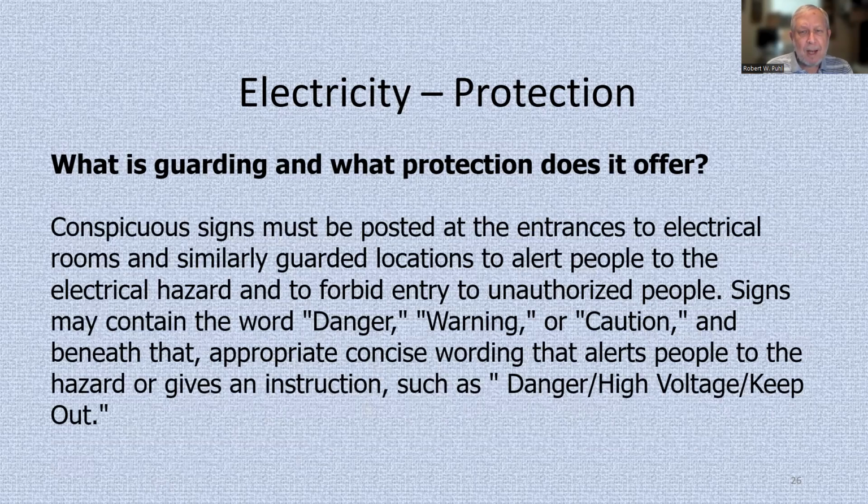Conspicuous signs must be posted at the entrances to electrical rooms and similarly guarded locations to alert people to the electrical hazard and forbid entry to unauthorized people. Signs may contain the word danger, warning, or caution, and beneath that, appropriate, concise wording that alerts people to the hazard or gives instructions, such as: Danger, High Voltage, Keep Out.